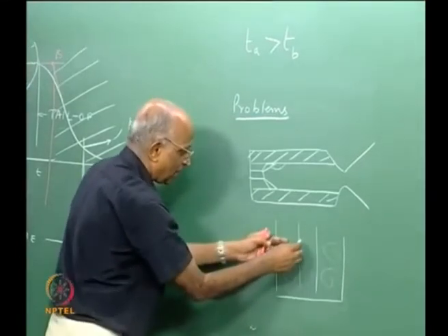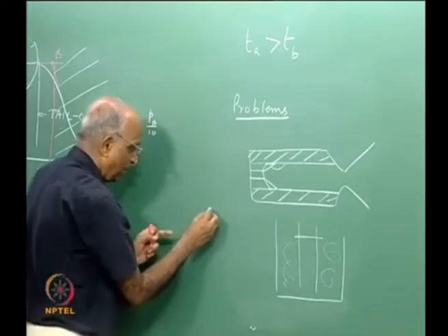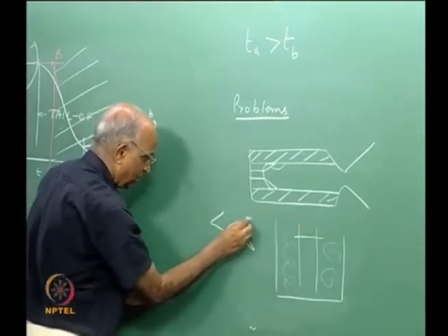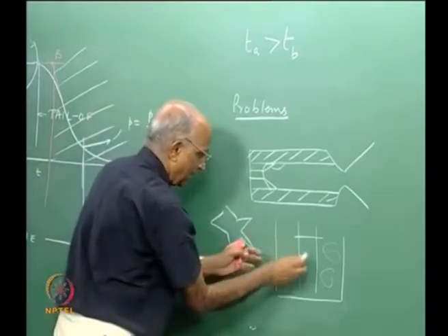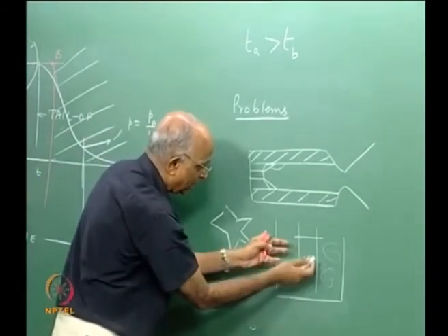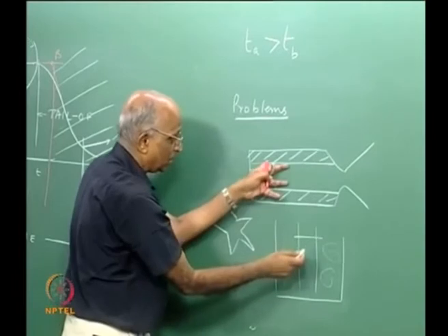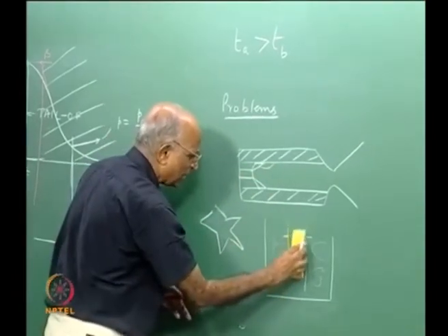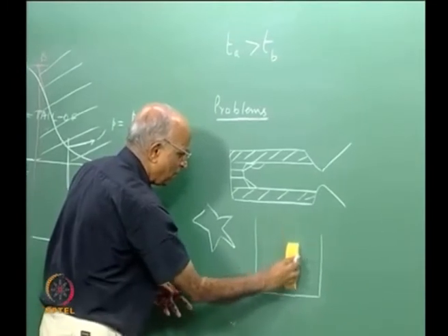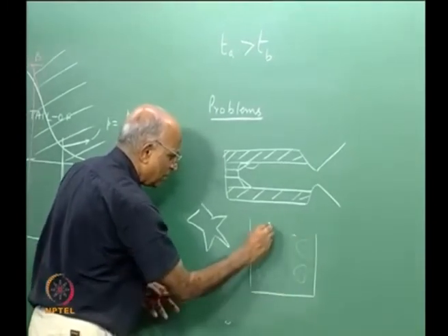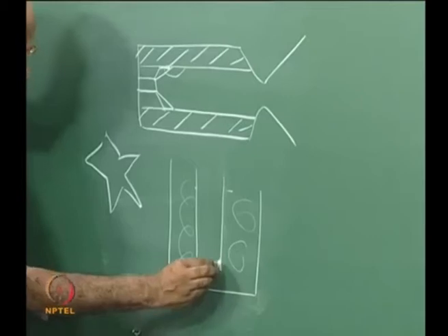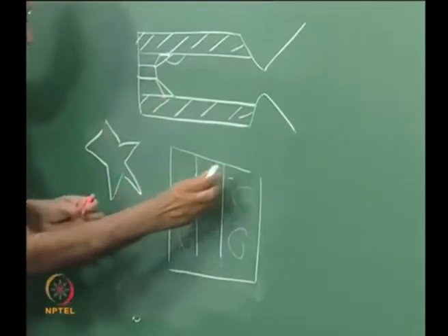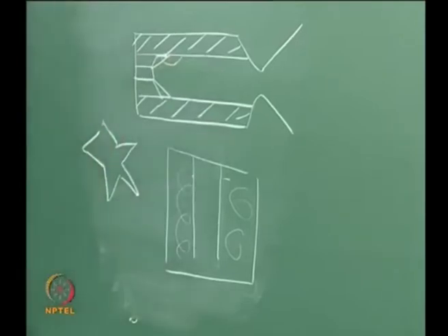If I want to make a star grain, the shape of the mandrel which I use should be a star shape, and then I cure it, and then I remove this mandrel, therefore I have this particular shape of the grain over here. On removing, sometimes it is difficult to remove the grain, and therefore we use some agents like silicone oil or something, which are essentially insulators, to be able to easily remove it, and I form the grain in this particular way.